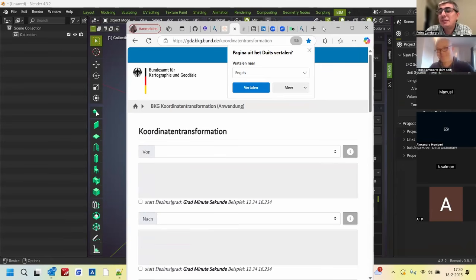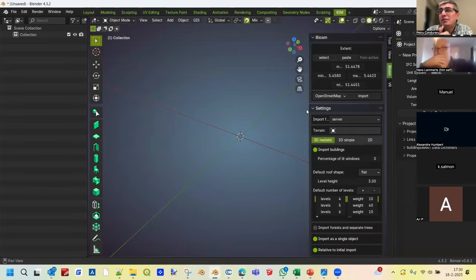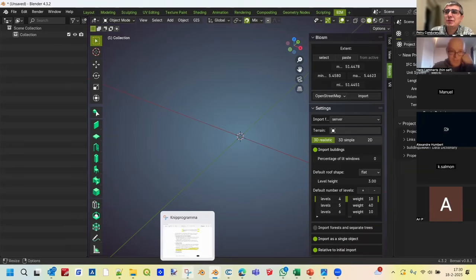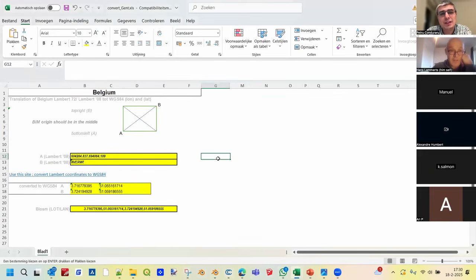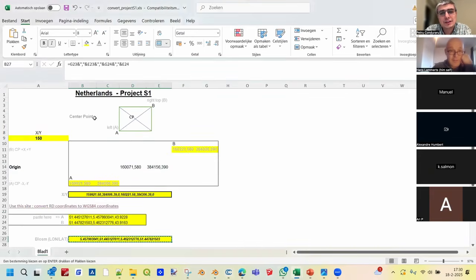Okay, look, another question because we have to take it right now. These coordinates you put into the georeferencing tool, the one you use the first time when you put your model in, like the center point, your BIM base point, should come from a surveyor, no? Because if you get them from an online map tool, you will never get it exactly, right? Just an estimate. This BIM base point is indeed specified by a surveyor.